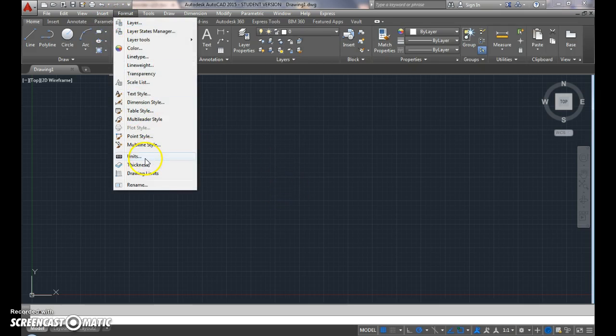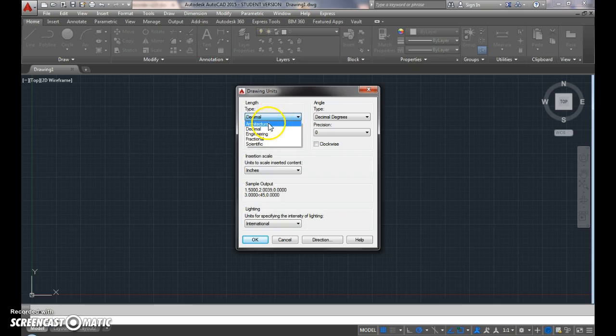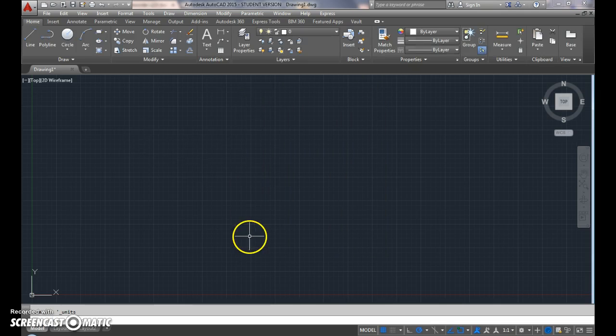First thing, obviously, as always, we're going to start by formatting our units, setting up for architectural units here, and going on from there. Whenever you draw a floor plan, you really want to say, okay, where's my starting point versus where am I going to end up? Just for bearings purposes, you have the view cube up here in the upper right-hand corner of your screen. South is the front of your house, almost uniformly, even if you were to put this house in another piece of land that, say, faced north and that was the front of the house. We always say that the front of the house is kind of down at the bottom of the screen, you're facing south. The back of the house is to the north, and obviously the right and the left sides would be east and west, respectively.